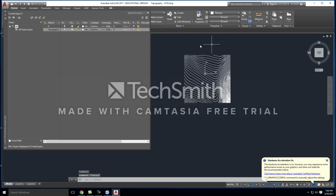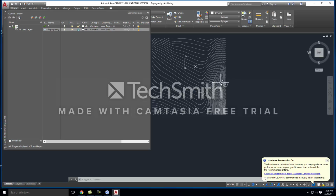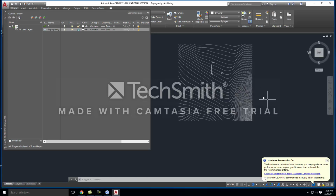The next icon is going to be the lock. The lock will keep the layer on the screen. You will continue to see it, but if you click on the lock, you'll notice that it goes into the lock position. Another thing you'll notice is that all of the line work became gray. Now I can't move it. I can select it, but I can't do anything to it. It's just there for reference.